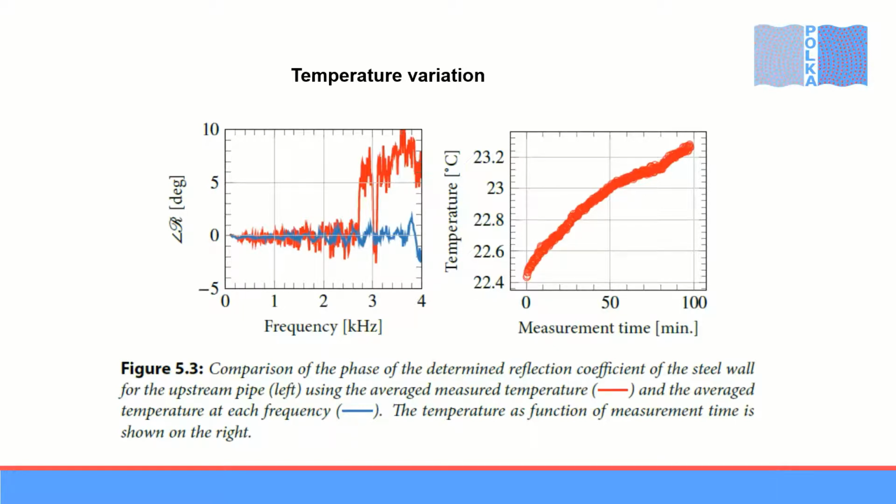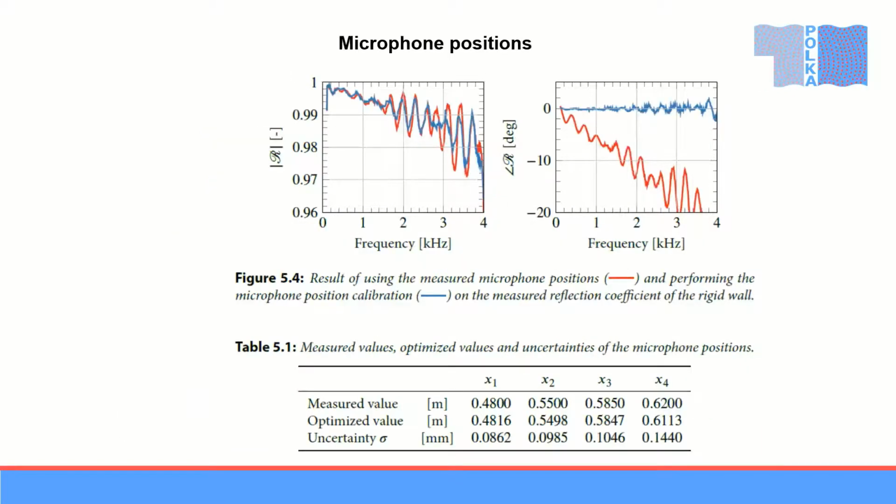So if you do a measurement for a long time and want to do very accurate analysis, you should actually keep track of the temperature variation during the measurements. The other thing Mats mentioned is optimization of the microphone positions. So to find out sort of the correct microphone positions,